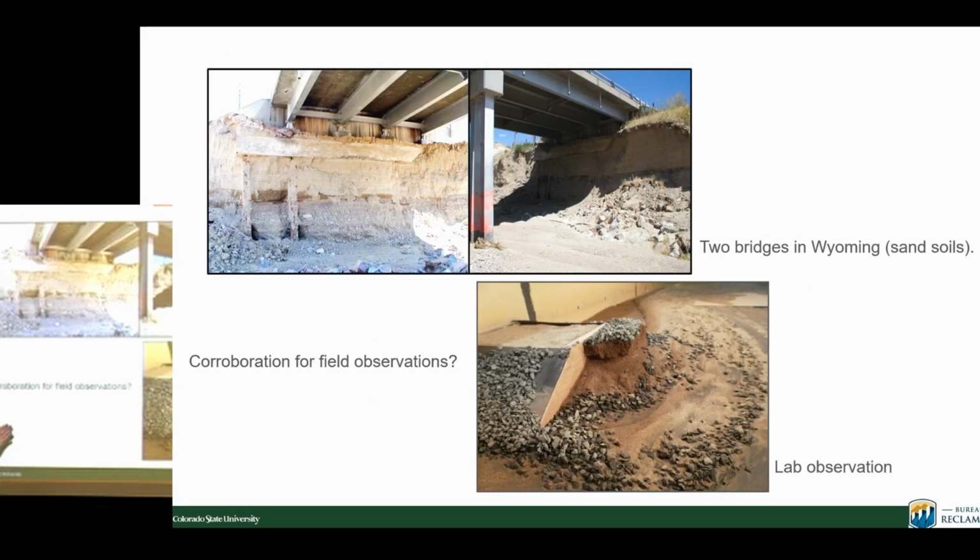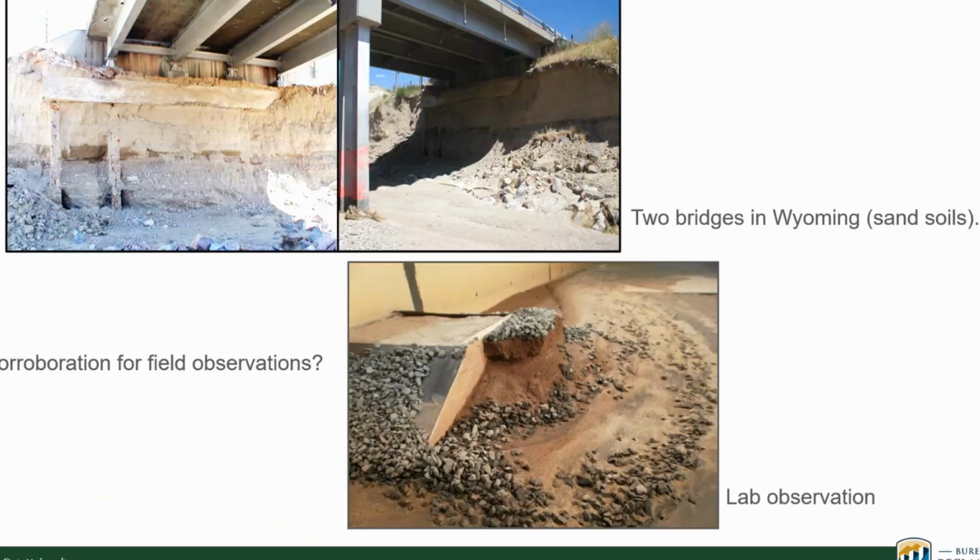So these are two bridges in Wyoming. You can see the geotechnical failure has opened up the bridge waterway. Contraction scour is basically limited, very similar to what we saw in the lab, where the abutment failed. Not much scour out through here, partly because of armoring, but also the geotechnical aspect. So the modeling of the soil strength is a challenge for us hydraulic engineers doing these sorts of experiments in the lab. You need a geotechnical engineer to work with you to model these sorts of things.